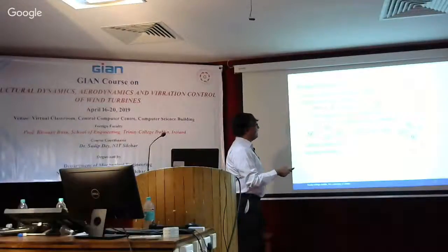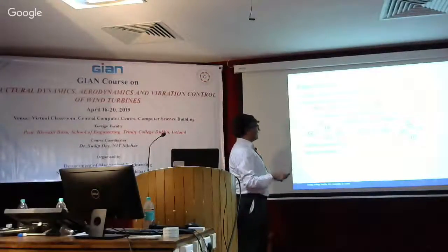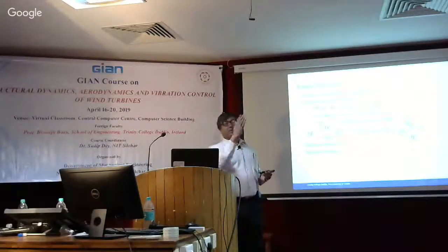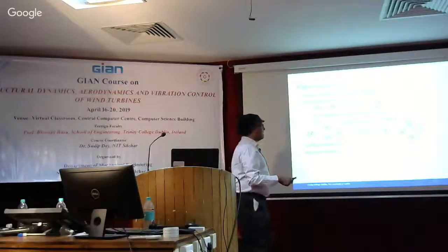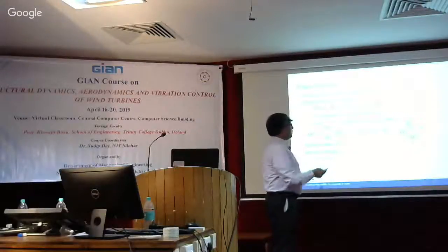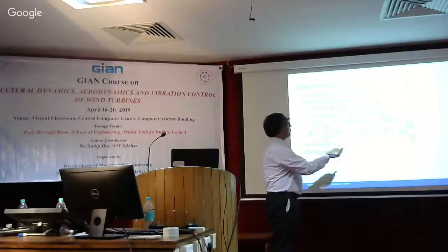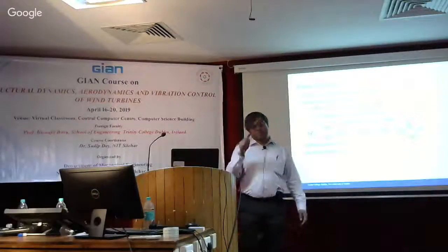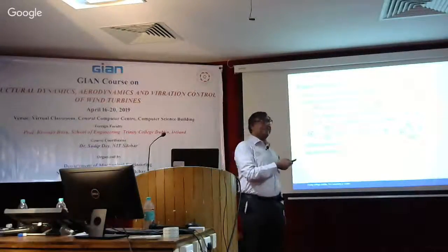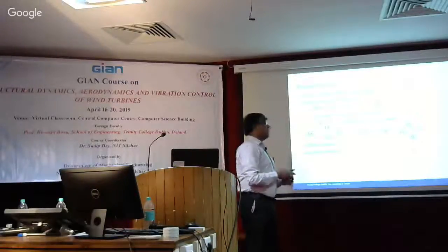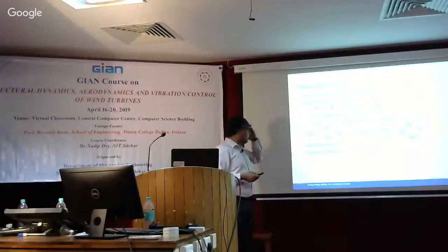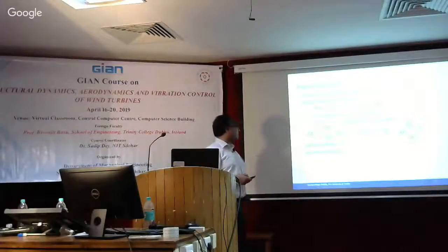And delta beta is minus d_p, which is the damping coefficient that we want to introduce, divided by del F del beta. And this can actually be characterized, meaning that if I apply a certain angle of attack and change it, we see how much the force is changing on the plane. If we do that calculation, use that factor, and we want this d_p to be added, then we calculate this coefficient minus d_p divided by del F del beta, multiplied by the velocity. We haven't measured the velocity, we measured the acceleration. Integrating, we get the velocity, and then this is our delta beta, and then we change the angle of pitch, and that will actually change the response of the tower. So this is essentially what was done, and additional damping was introduced.